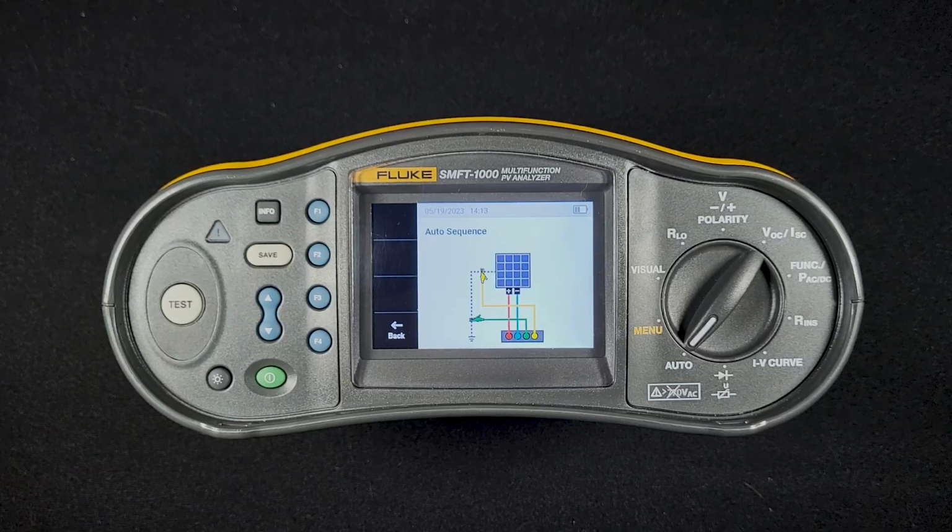You can use the 30-meter spool for the green wire in order to test the modules. Oftentimes, I'll put that green wire on the grounding bus bar in, say, an inverter or a combiner box, and I'll use the yellow one to go to the module frame to test between the two. You can also use that 30-meter green spool on the yellow side as well.